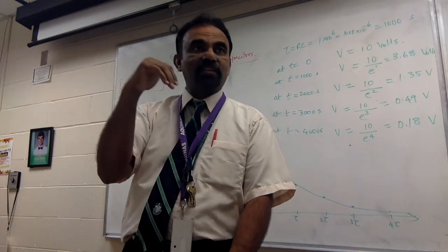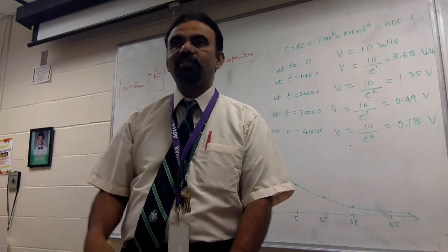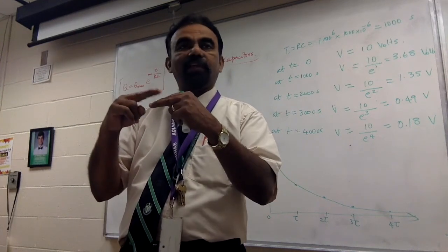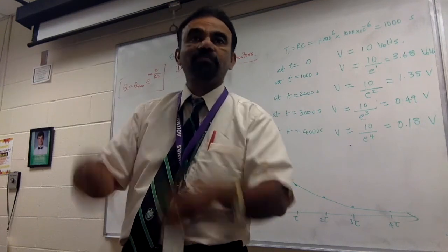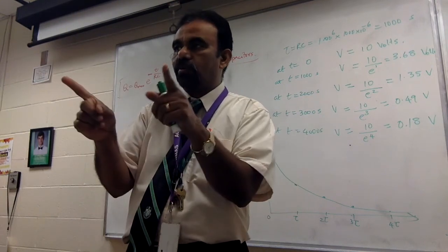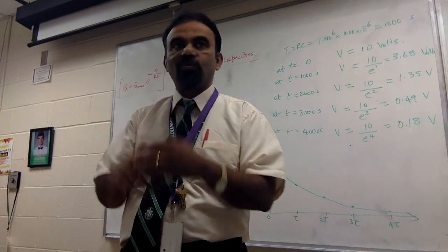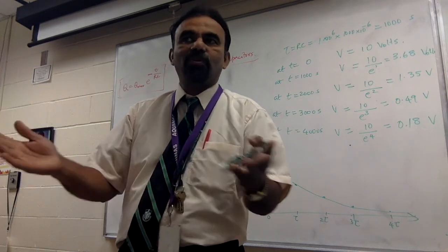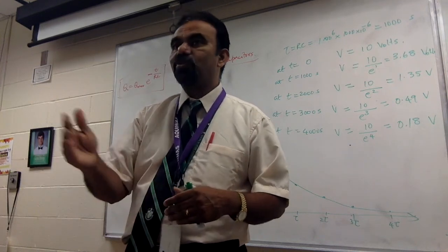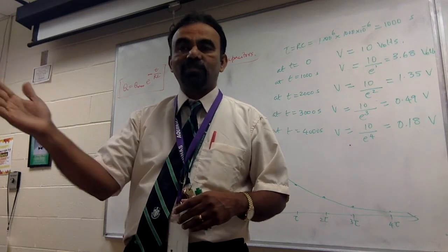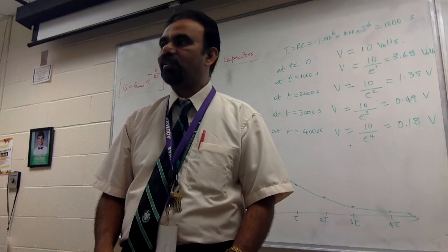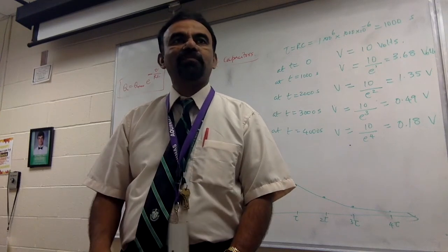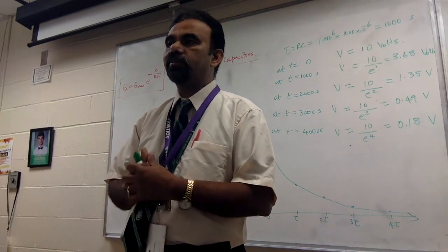As soon as it senses that, the relay trips to the other side, giving the voltage to the door lock. So the lock is now unlocked, and you are able to go without any problems. And now the door closes. There is a little period of time it waits before it locks, and that is controlled by timers.